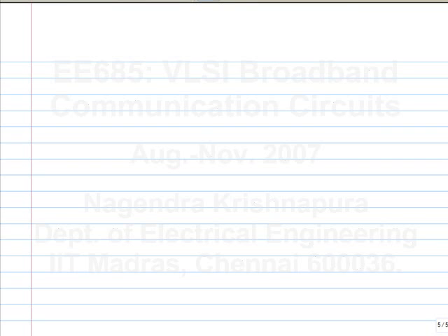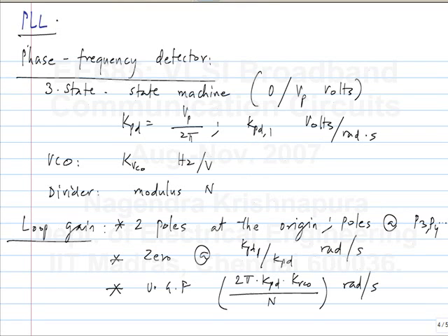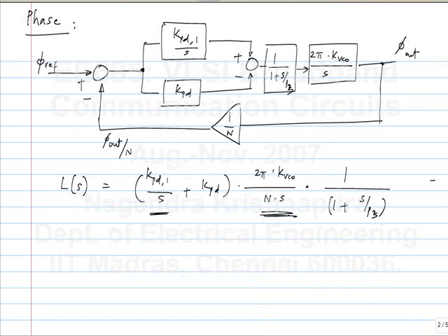Okay, the next thing is to make this part of the circuit. Right? How do we do this? We have something that takes the phase difference, but it gives you two outputs. If you take the difference between the two outputs, the average value of it is the phase difference between the inputs. Okay. Now we need something that takes the difference between the two outputs of the phase detector, as well as generates this functionality. How do we go about doing it?